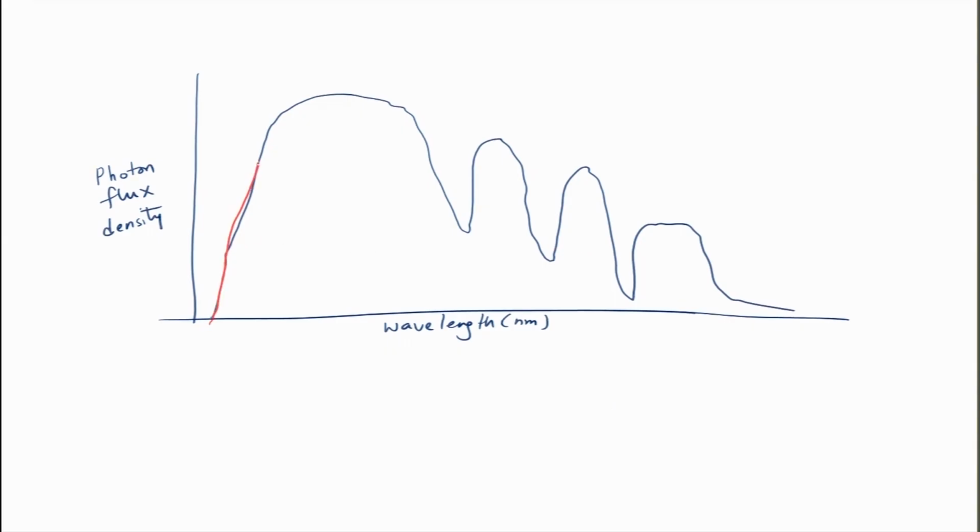you will absorb everything, you will not lose anything, as far as the solar cell permits, right. It will not absorb anything below the band gap. So, starting from here up to the band gap, it will absorb everything. So, this would mean that your quantum efficiency is equal to 100% because you have absorbed everything that was available to you, and which has led to formation of electron and hole pairs.